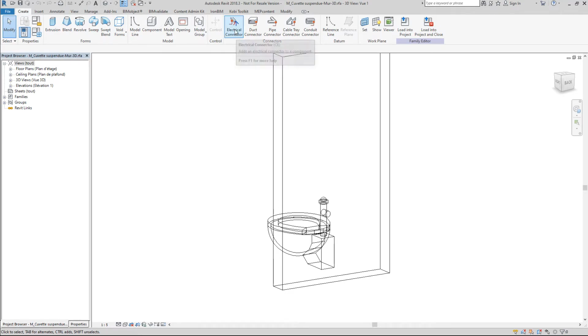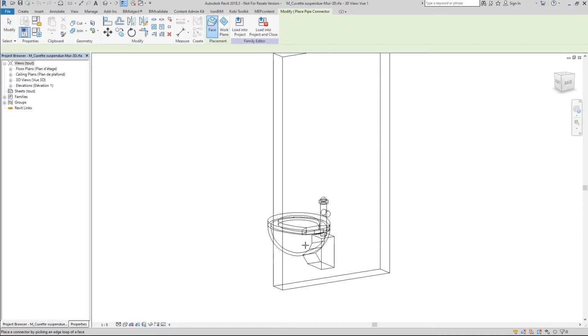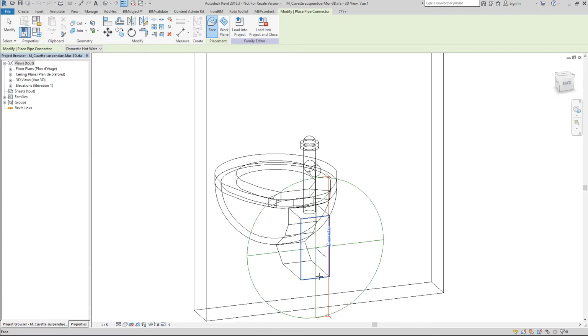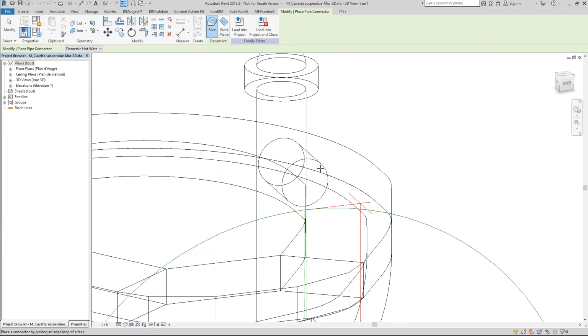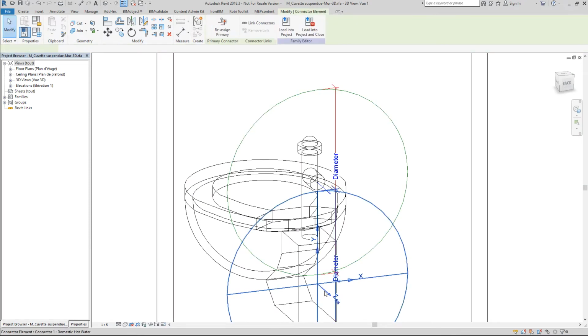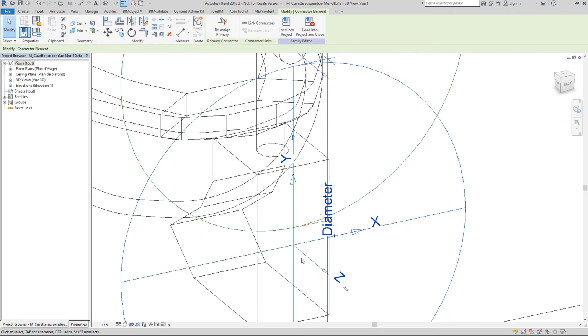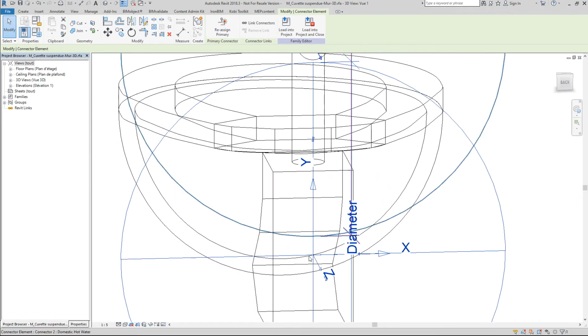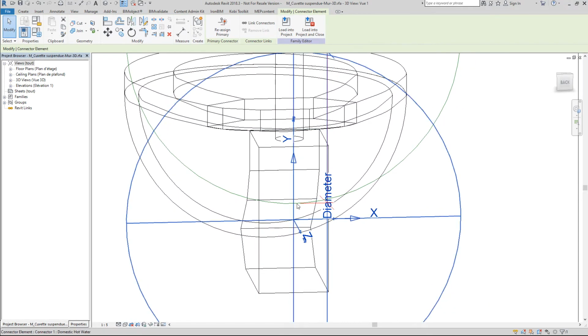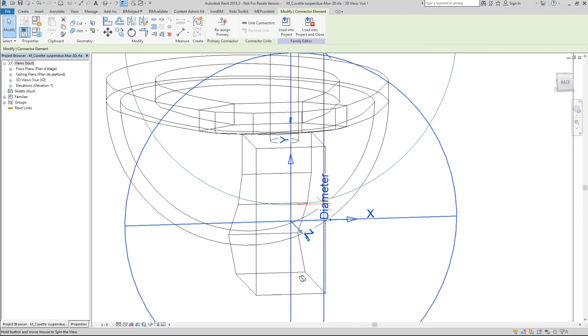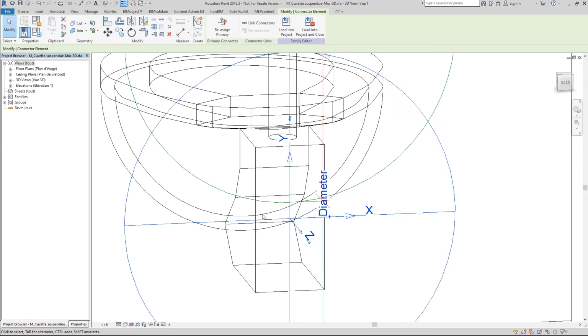So this is sanitary, so we will have to create a pipe connector. The pipe connector can be phase-based, and is mostly phase-based usually, but it can also be plane-based. Every connector has coordinates, as you can see here, X, Y, and Z. XY is usually about the face on which the connector is implemented, and it should always be in that sense.